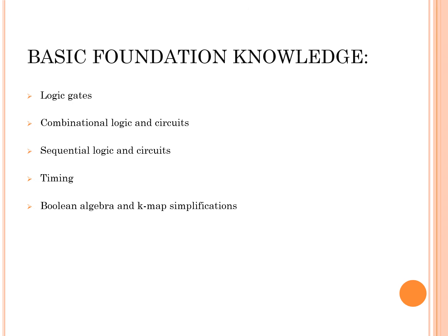Next, we move to sequential logic, which adds memory into the picture. Using flip-flops, latches, registers, and counters, we also explore finite state machines, memory units, clocked sequential circuits, and programmable logic devices like PLDs. You will also need a solid grasp of timing concepts like setup time, hold time, clocking, and understanding metastability to ensure reliable circuit operation.